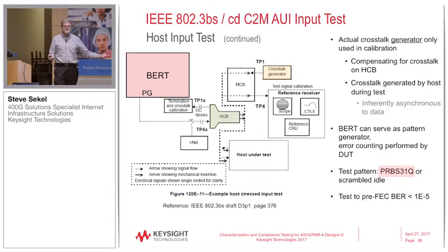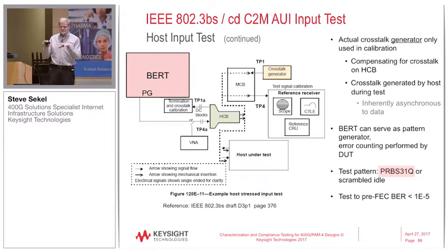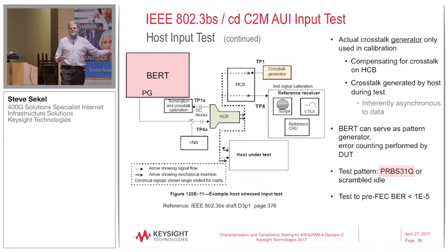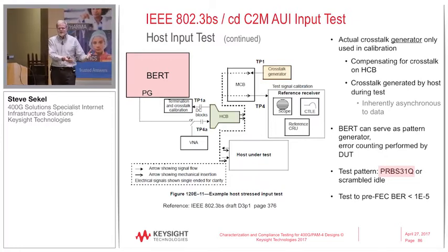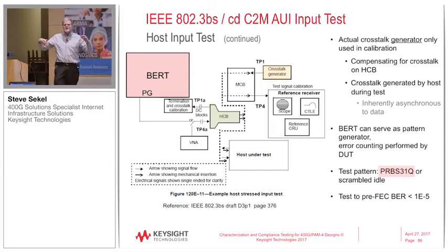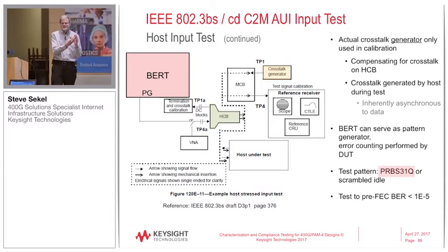But what these guys will tell you, and it's very true, you can play with it in the lab, is that the transmitting process alone in PAM4 has corruptions in it, that even with an instrument grade error detector, the error detector is going to get some additional errors just from the process of retransmitting the data.